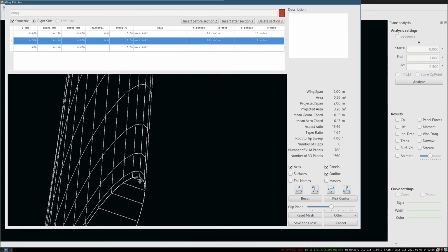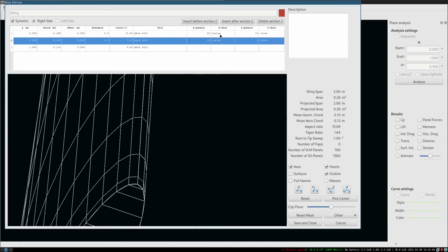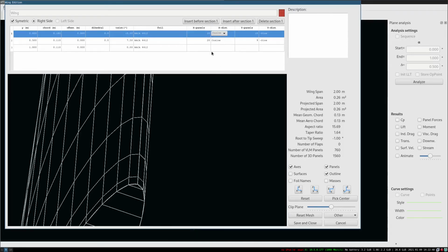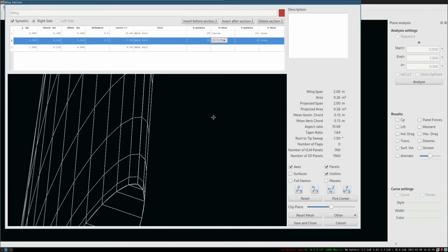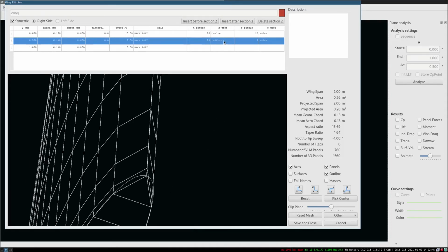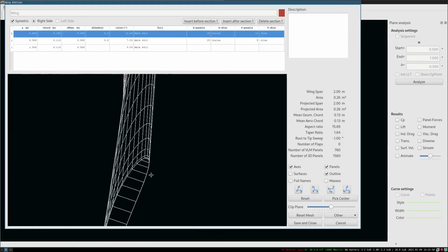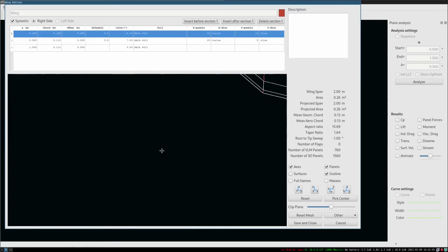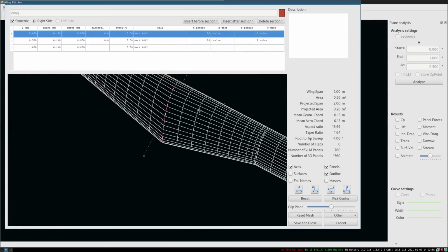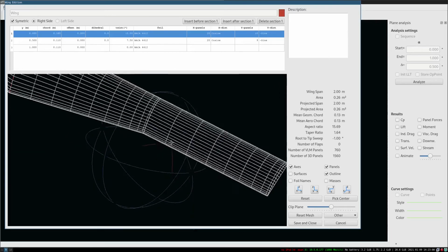We can see here you've got this triangle section. This is not great. Now, the way that you can fix this is, well, the way you make it worse, typically anyway, is by going to uniform. Uniform's bad, so you can use cosine distributions where it will concentrate the majority of the panels at the leading and trailing edge, which is exactly what it's done there. Typically, you don't have much curvature on the middle edge of the wing, so you don't need a huge number of them there.